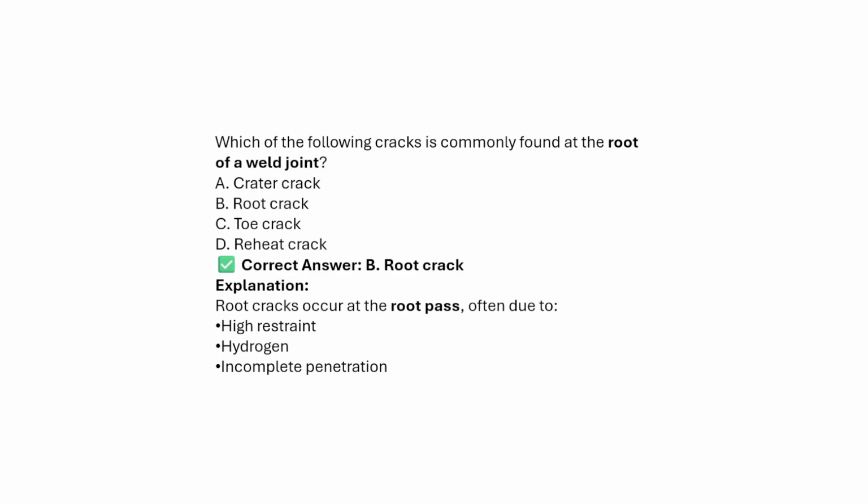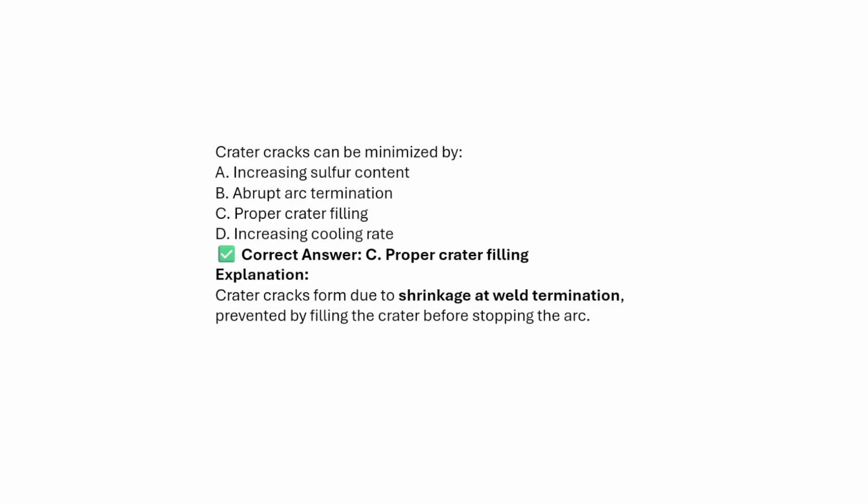If not enough heat input is given, there is incomplete penetration of the molten pool, and that also results in root cracking. Next, how can crater cracking be minimized? A, increase the sulfur content. No, if we increase the sulfur content, it will result in more crack formation.